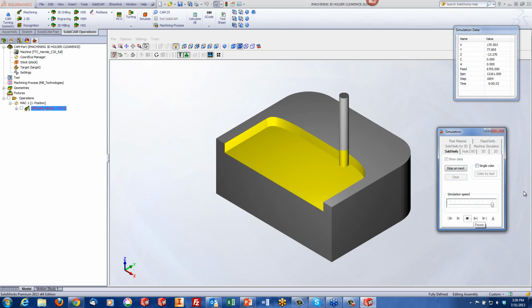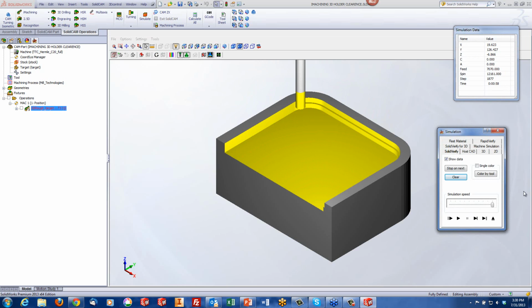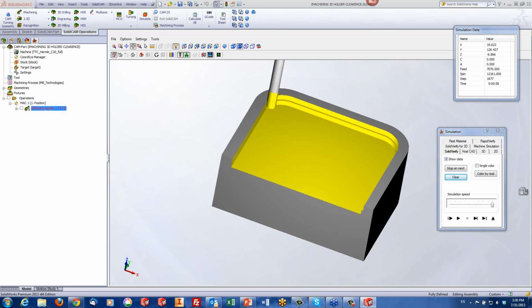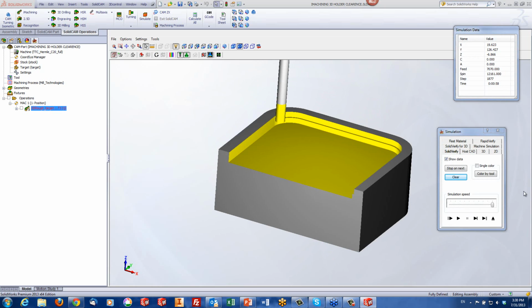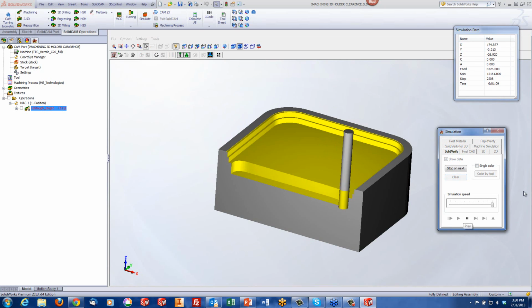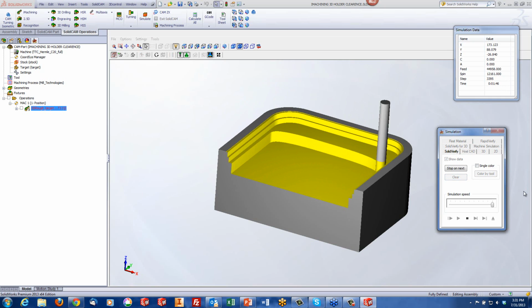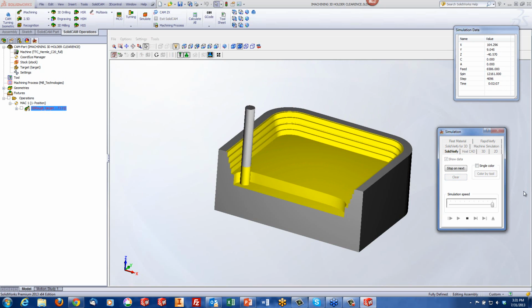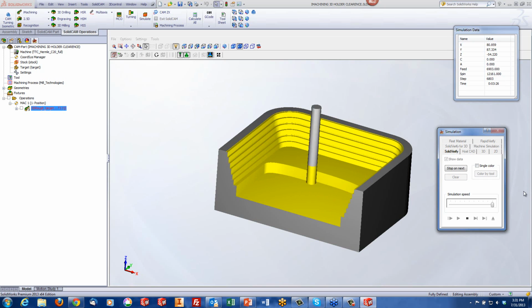Now, it's going to finish the step, and note what happens now. You note now, I would stop at this moment. It started clearing our rest rough already at this point. Now it finishes. Now when it finishes that rest rough, it's going to the next step, and then it's going to finish the rest rough just on the step itself. And that's the way it's going to work on this part. In other words, you're giving yourself more clearance now on the side of the tool, as you're going down on the part itself, by taking away the rest rough before it goes down.